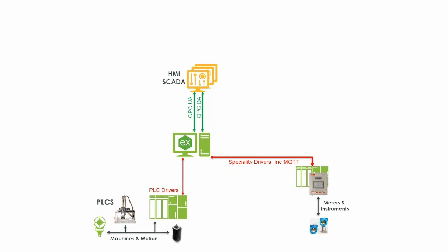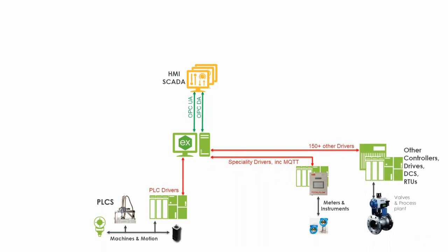In addition to that, there's a whole raft of speciality drivers that Kepware have got for instrumentation and meters and things like oil and gas systems, all sorts of things of that nature. You've got drivers for DCSs, RTUs, inverters, other types of controller. So you can go into a factory and you can do an audit of what's around and what's got COM ports, and pretty much everything you will be able to find a way of getting Kepware to talk to it.